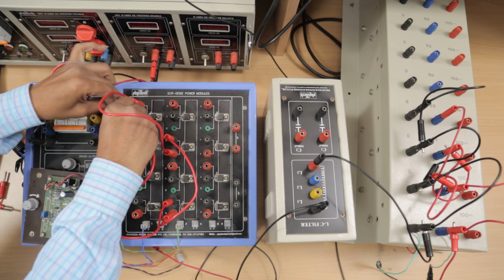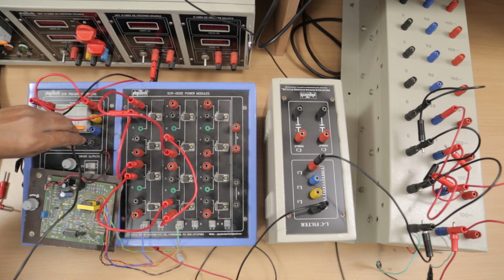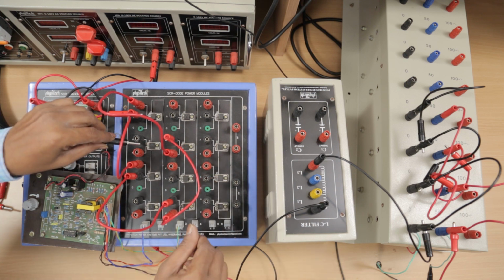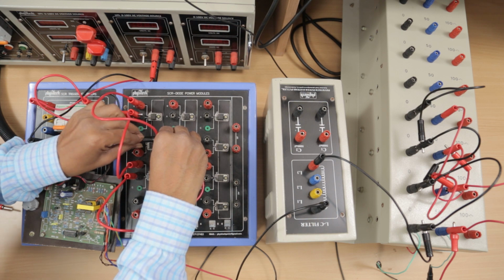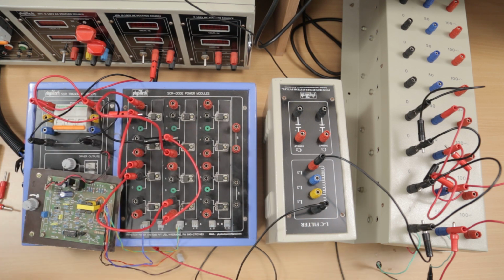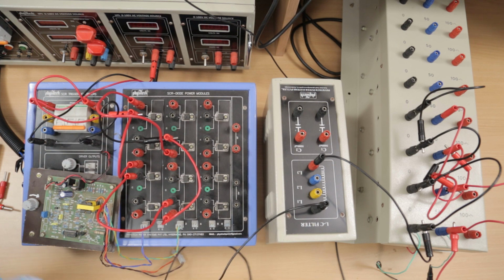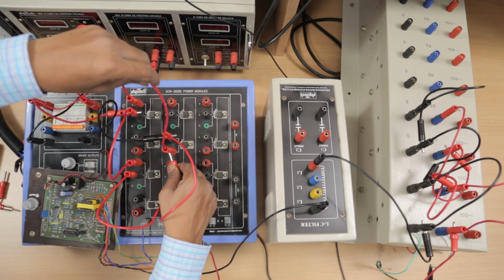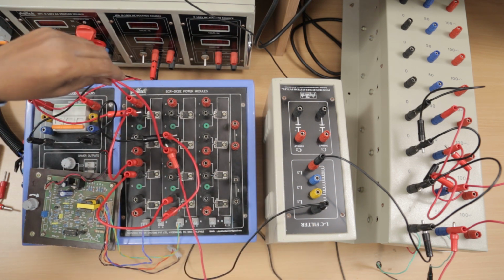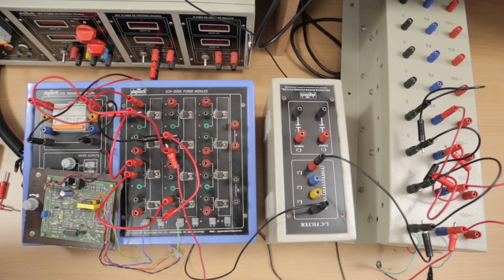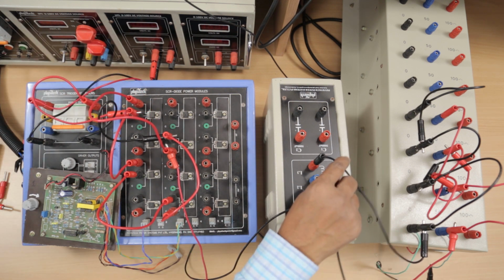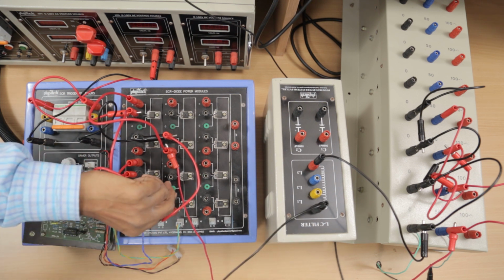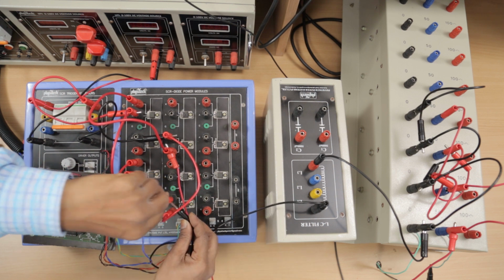Now from the MCB output terminal, R phase goes to where the anode and cathode of D1 and D2 are joining. From the MCB output neutral to the D1, D2 anode cathode joining point. From the resistive load to the T1 cathode and D2 cathode joining point. Both the cathodes are joined. There we are making the resistive positive terminal. From the resistor's other terminal to the inductor, and the inductor's other terminal to the T2 thyristor and D1 anode joining point.